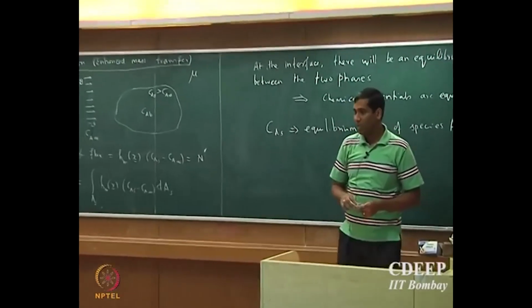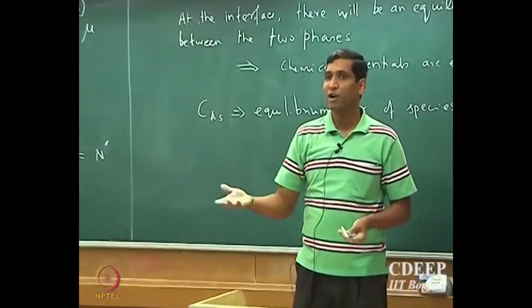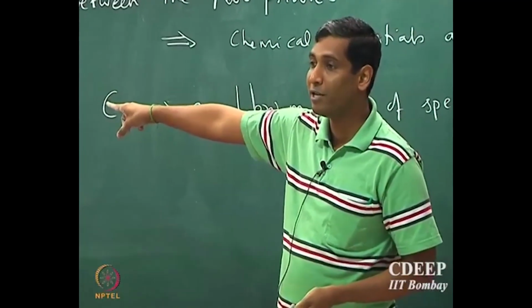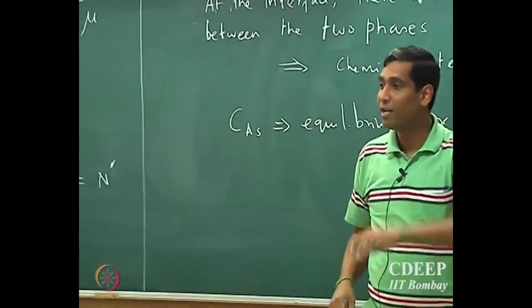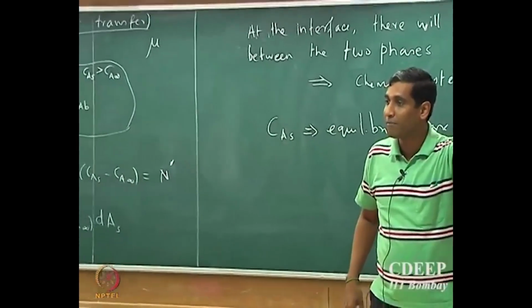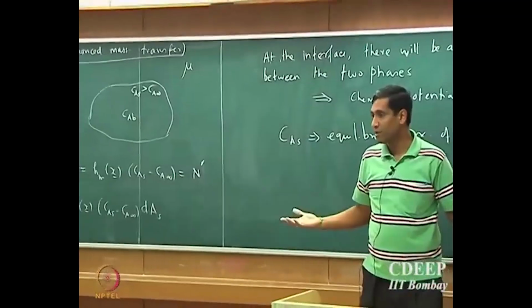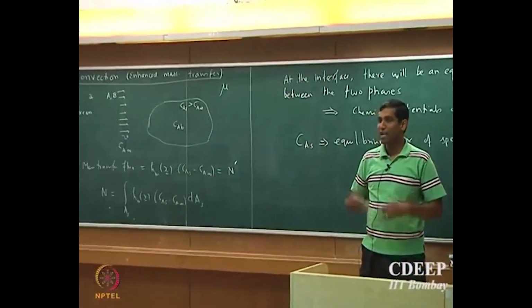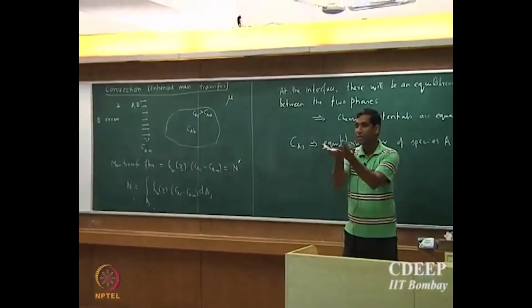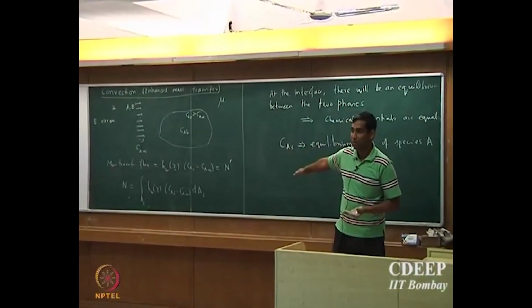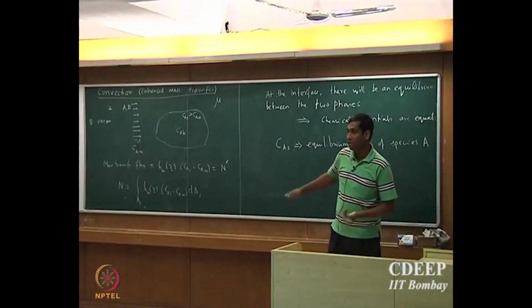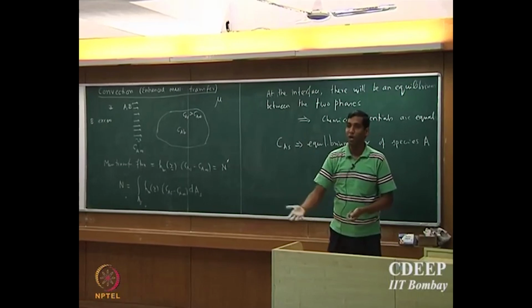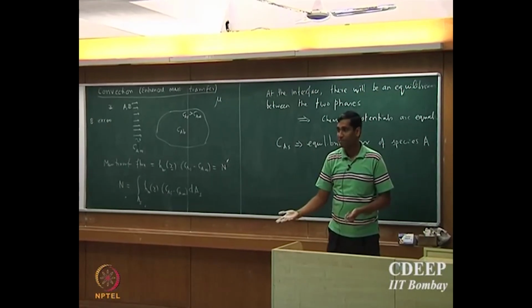Right, if you assume the heat transport case, the question is, will there not be a temperature gradient? So note that I said it's a well mixed system. So C_AB is the bulk concentration everywhere. Similarly, if you assume that it's a well mixed system where the temperature is uniform, it's the same scenario. The only difference is that there the system actually can take more energy and it will lead to an increase in the temperature. That's not the case with mass transport. There is an upper limit on how much you can pump, and that is based on the solubility of that species in that medium.